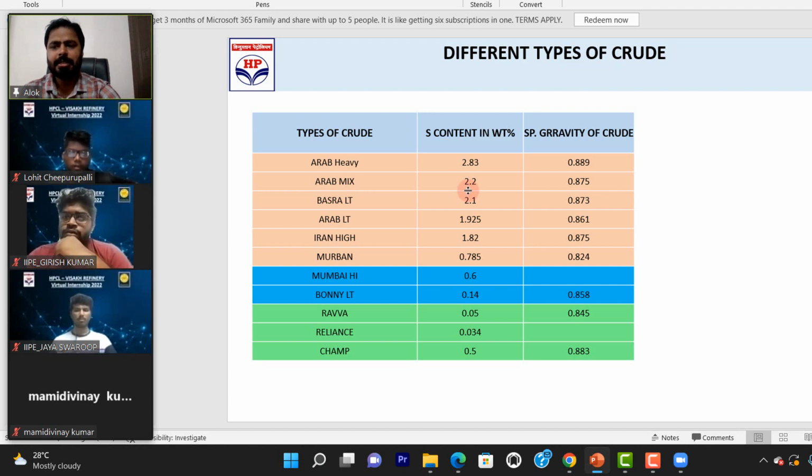So SCSV means spent catalyst slide valve. That is basically being controlled as per the reactor level. So we give a set value to the reactor level. We want 40% level or 45% level. Whatever level is in excess, you have to transfer it to the regenerator. So when the level goes above 45,